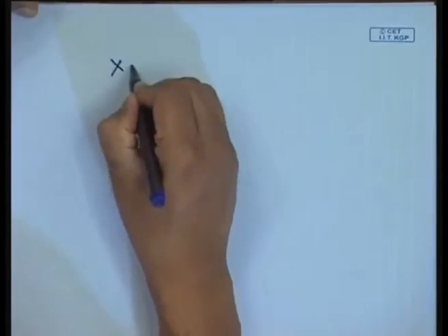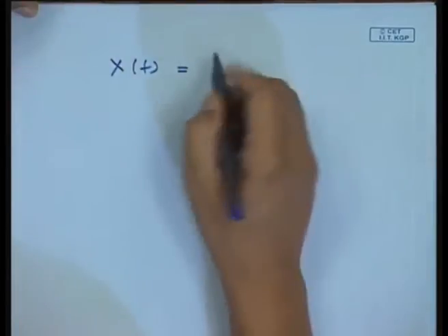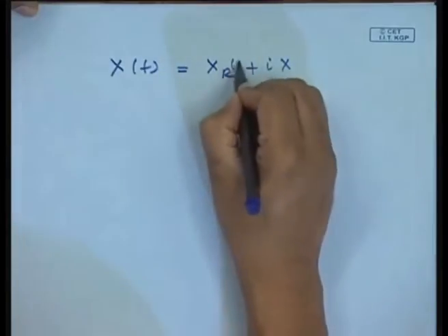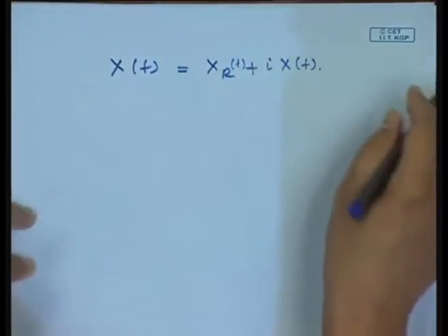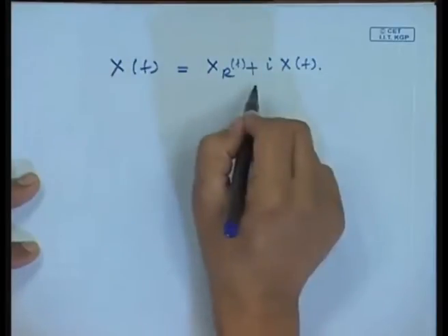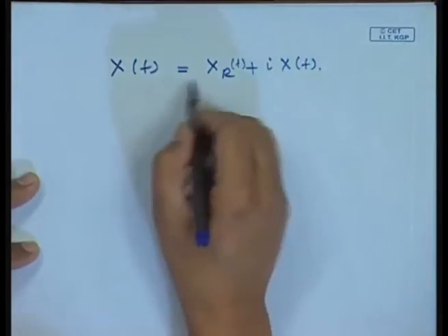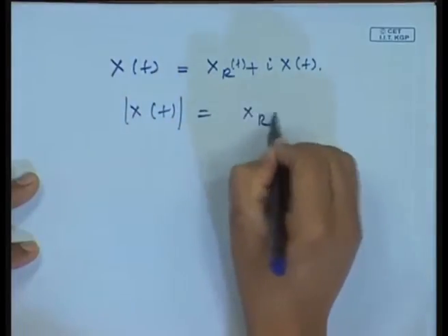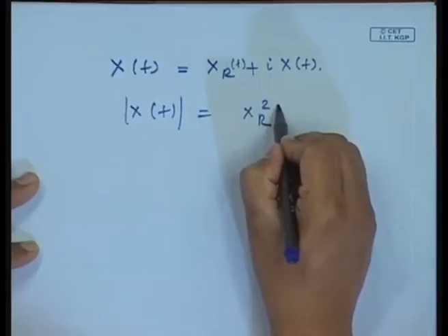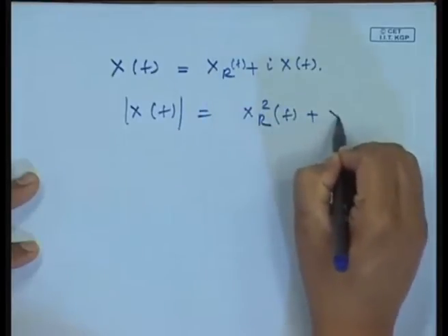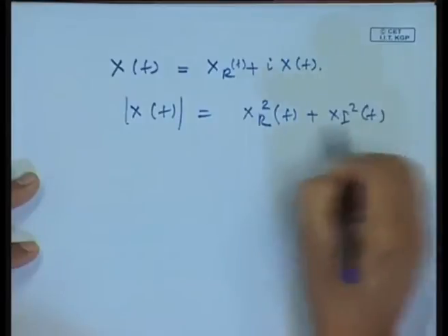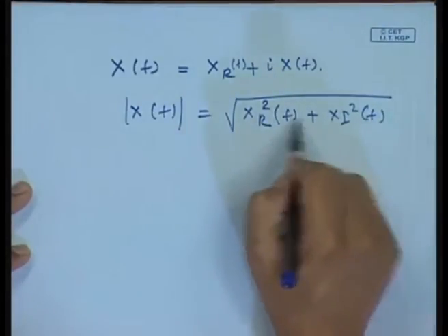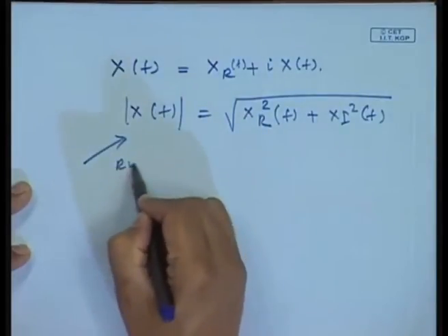So, if this FFT has been obtained, I can obtain the linear spectrum. Magnitude of the linear spectrum is nothing but the magnitude of the FFT, so unit becomes linear, and you will see magnitude means this is a real quantity.